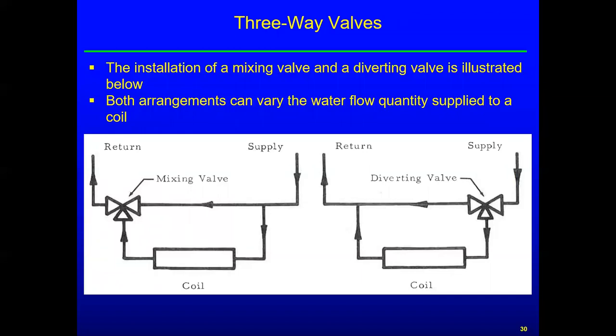Well, remember, when we have a pressure drop, we can liberate dissolved nitrogen probably from the water flow. And so if we put that valve on the back side of the coil, on the downstream side of the coil, then that air liberation would go into the return line. And if we have 2 feet per second, then that air would hopefully get brought back into the return header, return distribution piping, and make it back to the air separator and get pulled out of the system.